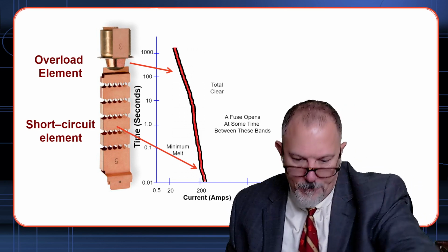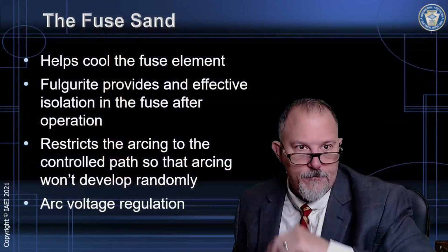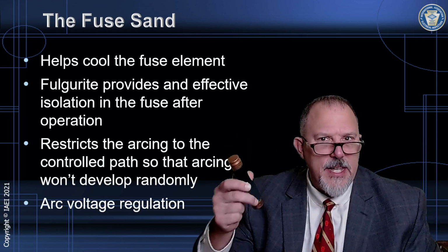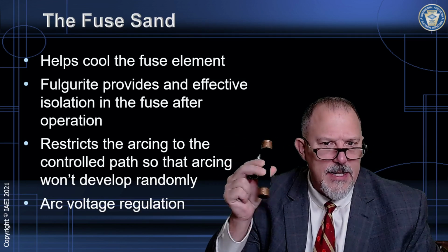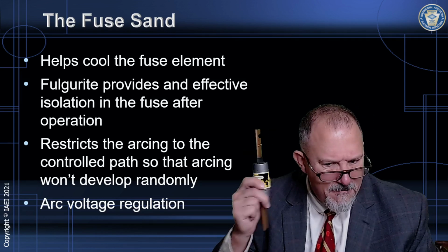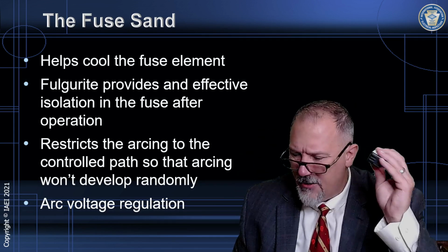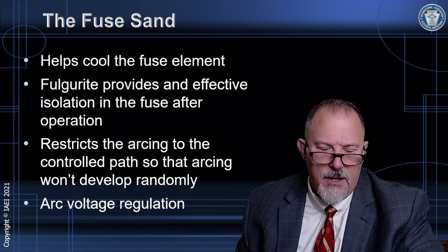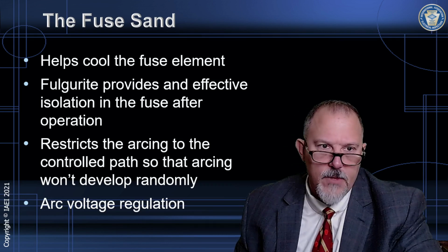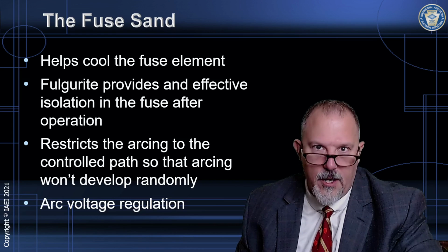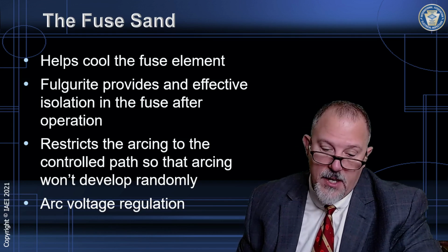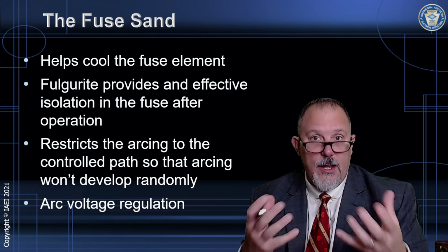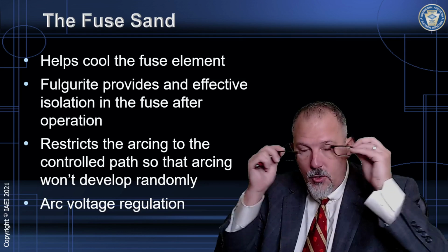All right, so let's move on. Now the sand. You shake these devices. In some cases you might hear a little bit of sand movement in this one. I don't hear any sand movement in that one, and I don't hear any in this one. The sand, what does it do? Well, it does a lot more than just what we explained here by turning itself into fulgurite. It helps cool the element as well, because you're heating an element inside and you have a material around it that helps absorb heat. So it can help cool the fuse.